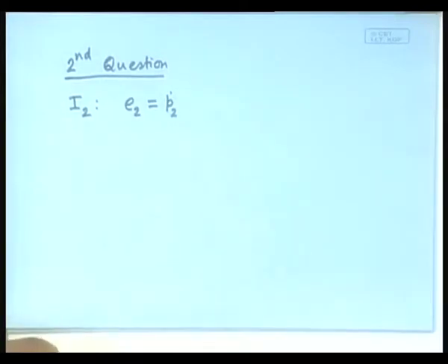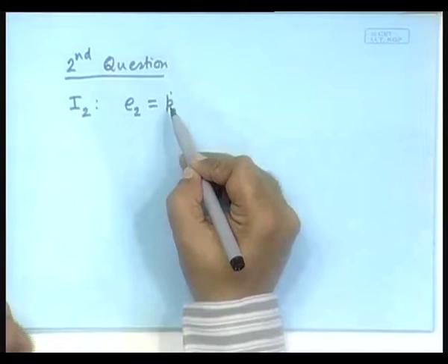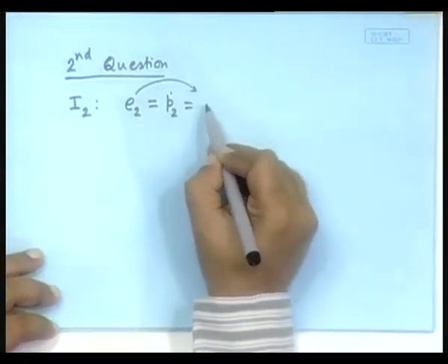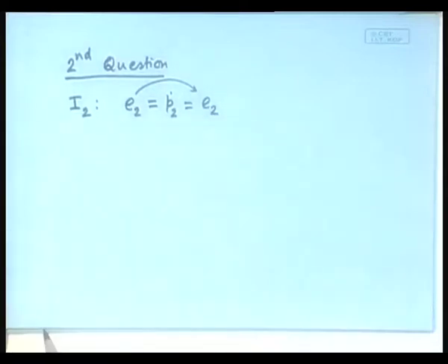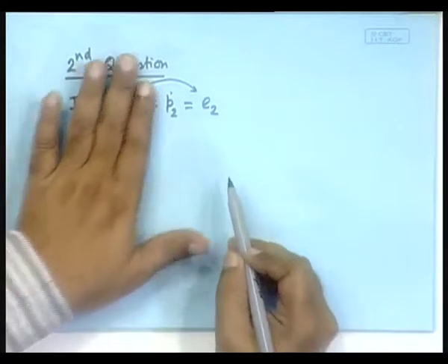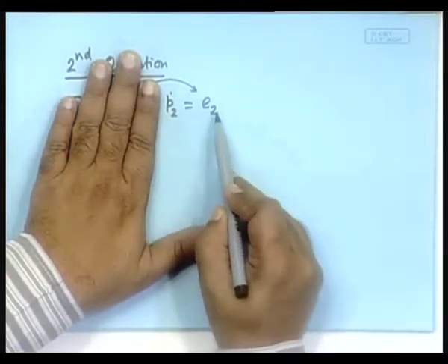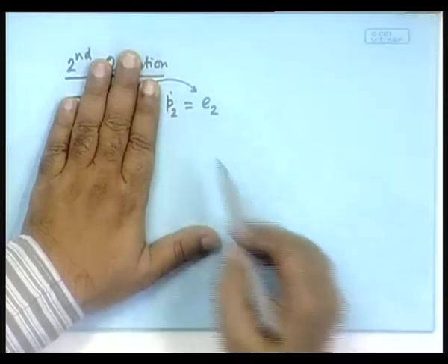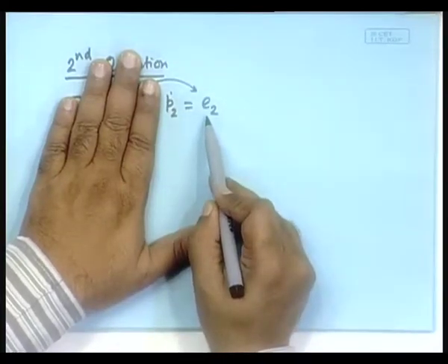Okay. So, we have the dotted term, we normally express that in the left hand side. So, we bring it here, and P2 dot is equal to E2, we can write it. So, we have got the differential equation with P2 dot equal to E2, but we do not know E2, and we have to scout the whole bond graph to find out where this information is generated.